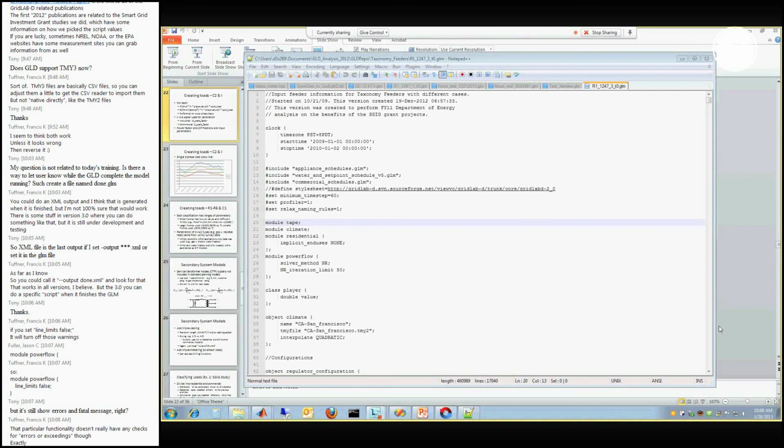It's a good indicator to tell you maybe you've got your loads configured wrong. If you see a line that says I'm at 800% of my rated limit, it's a good indicator to go check that load. Oh yeah, I did add an extra 0, my bad. Well, we're intentionally putting little 0.5-megawatt solar farms at spots along the feeders, so we know. We're trying to blow things up and make sure that the protection is working. And if you just add that flag into your module power flow, it'll turn all those warnings off, so you don't have to see them.